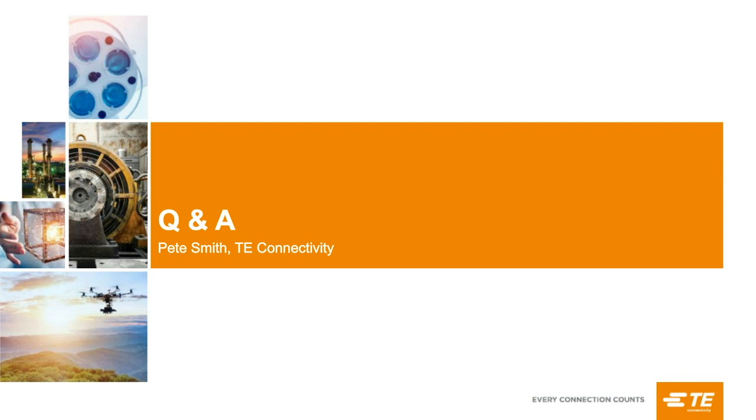And on that ASIC is a single microcontroller. And then we use a multiplexer to multiplex between the sensing elements to monitor the readings that they're taking. There are 3 sensing elements, but they all connect to the same ASIC, which contains the multiplexing capability and does the processing.